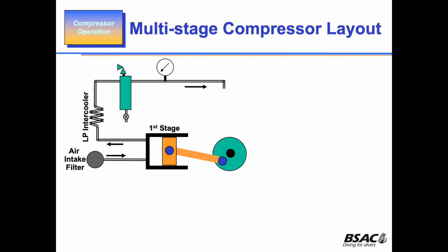And so it leaves the intercooler and goes into the condensate separator. In there, it's like a filter. We'll cover that a little bit later. In there, the moisture and any other liquid impurities are filtered out, and we drain them through a drain valve. You'll find out about the drain valve. It's a very important thing. And of course, the filter will have a relief valve on it to stop it from being overpressured. And in sophisticated compressors, you have a stage gauge to tell you what the pressure of that stage is.